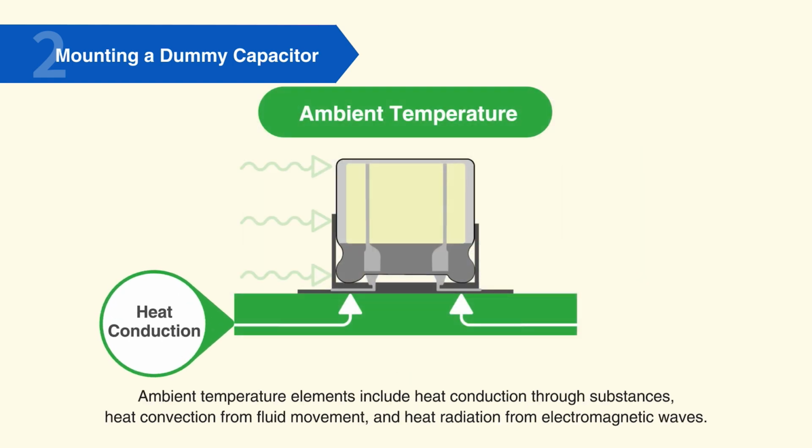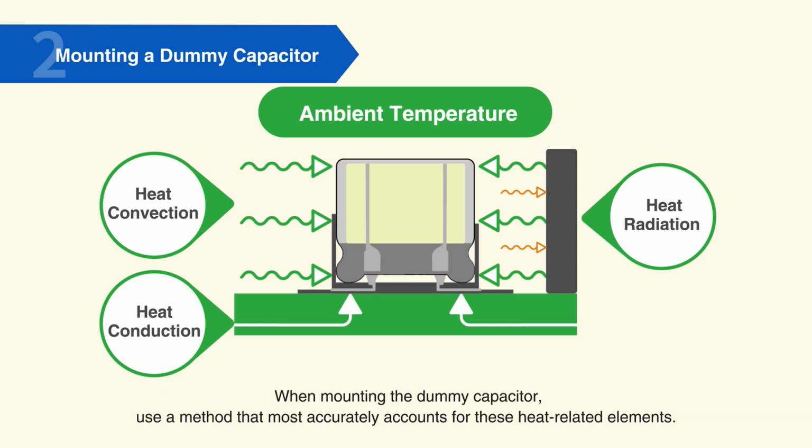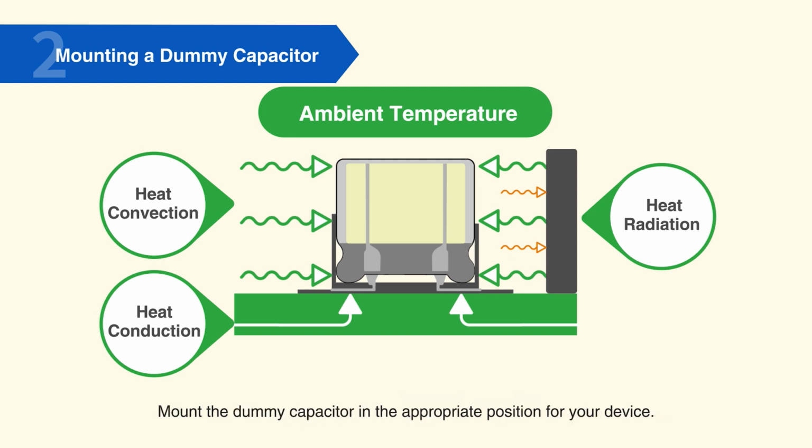Ambient temperature elements include heat conduction through substances, heat convection from fluid movement, and heat radiation from electromagnetic waves. When mounting the dummy capacitor, use a method that most accurately accounts for these heat-related elements. Mount the dummy capacitor in the appropriate position for your device.